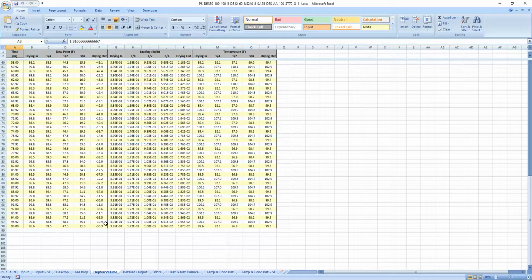The inlet end, the desiccant loading is about 39%, which is pushing the maximum capacity of activated alumina. On the dry end of the bed, we're somewhere down around 2%. So at 2%, we're achieving this minus 11 degree dew point.